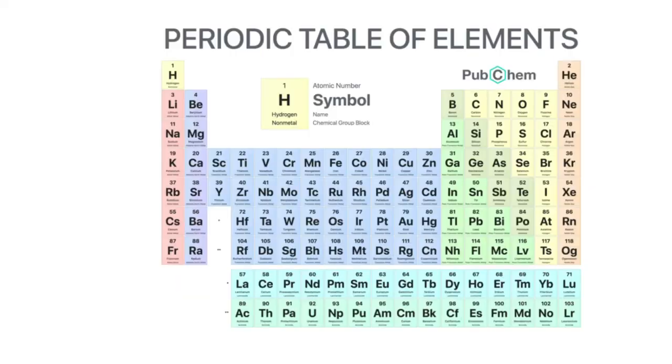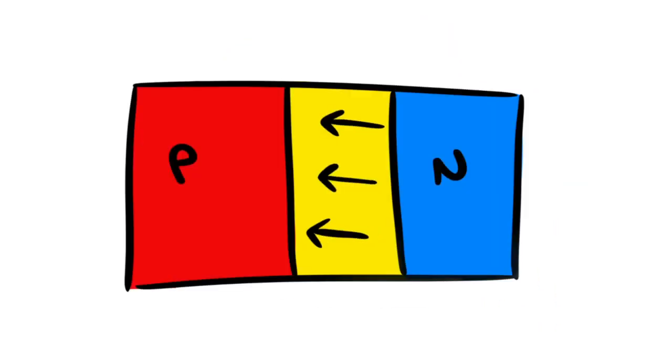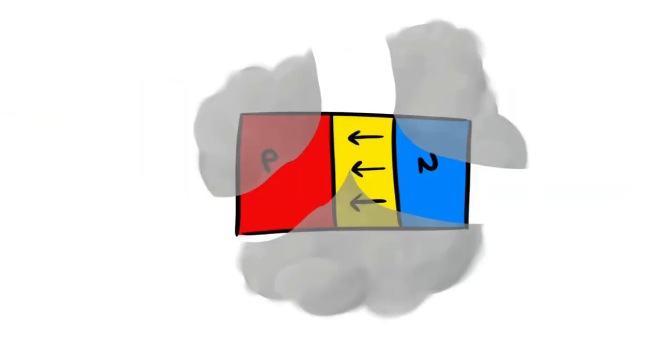Simply put, the bandgap of an element is just energy states that its electrons are not allowed to occupy. Inside of the photovoltaic cells, there are also PN junctions, which generate permanent electric fields to direct the flow of electrons. They are formed by joining two pieces of silicon with elemental impurities in them.